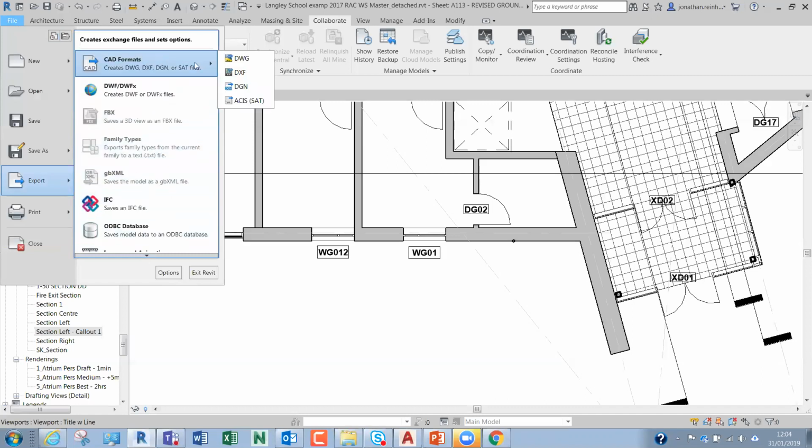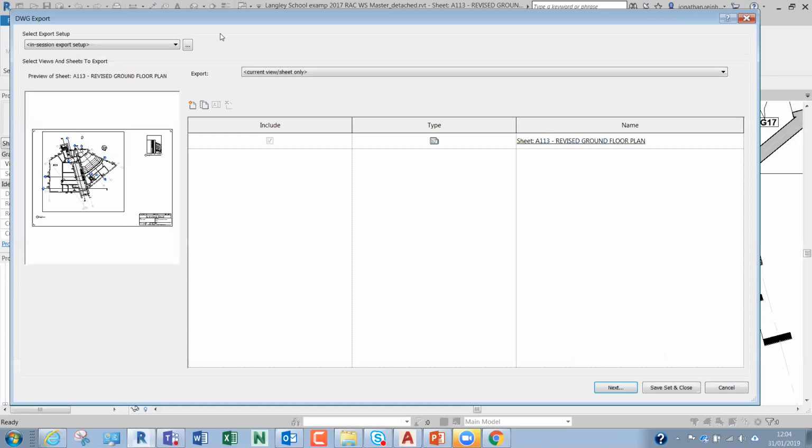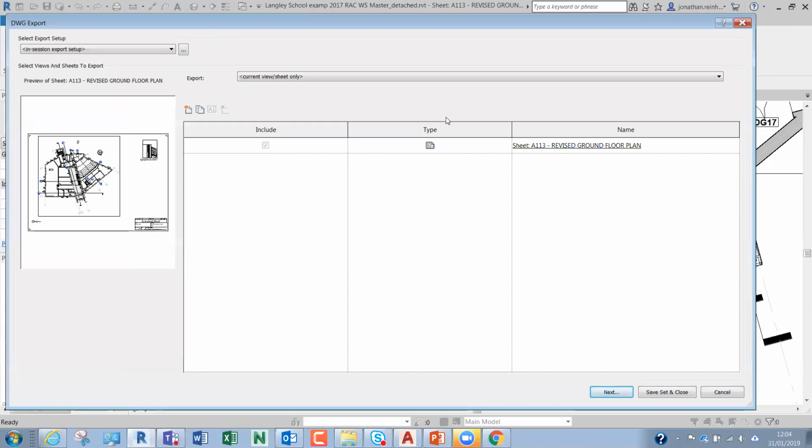You're able to share that as well. But you can also export any of your drawings as a DWG, and these are all snappable drawings, openable within any AutoCAD software, and you're able to either reuse those floor plans if you want, or if you have to send floor plans to a consultant, you don't just have to send them the Revit model, you can send them independent CAD drawings as well, if that's what you need.